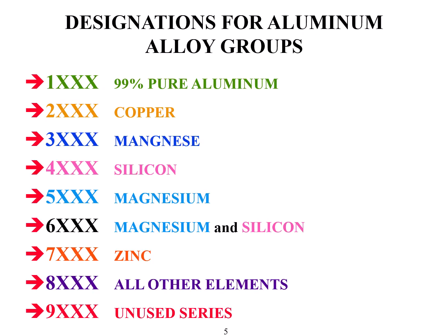Designations for aluminum are based on a numbering system. And as you can see here, 1 through 9, if it begins with a 1 in this four-number code, that's pure aluminum. 2, the major alloying ingredient is copper. By the way, that's the one that is used the most of all the aluminum alloys in structures.